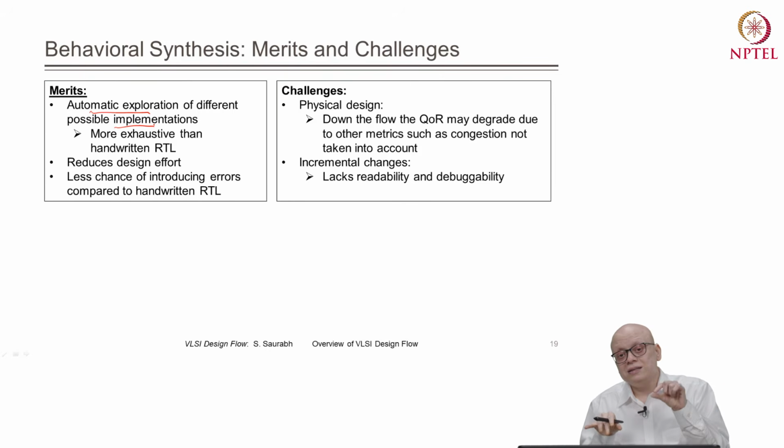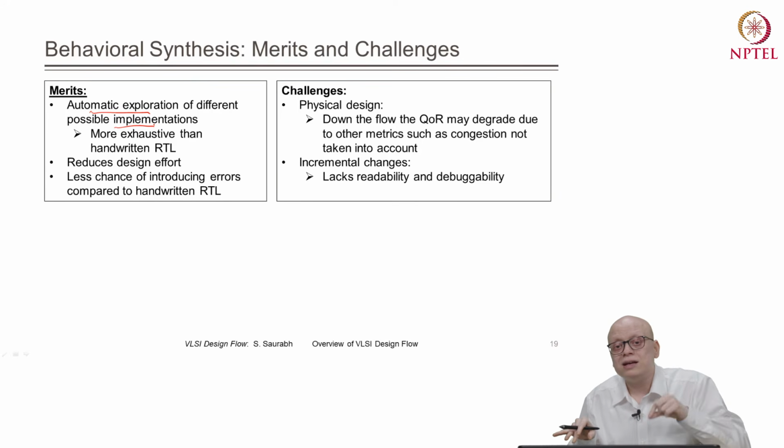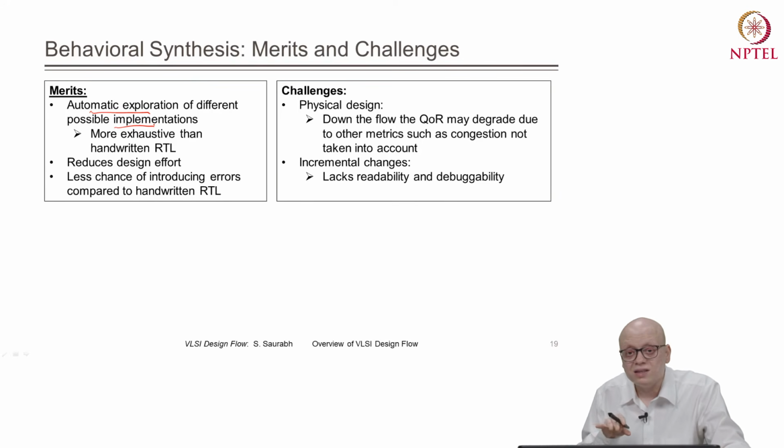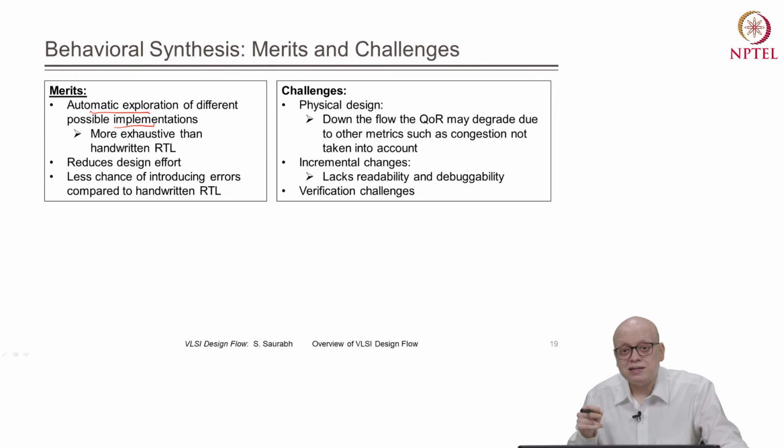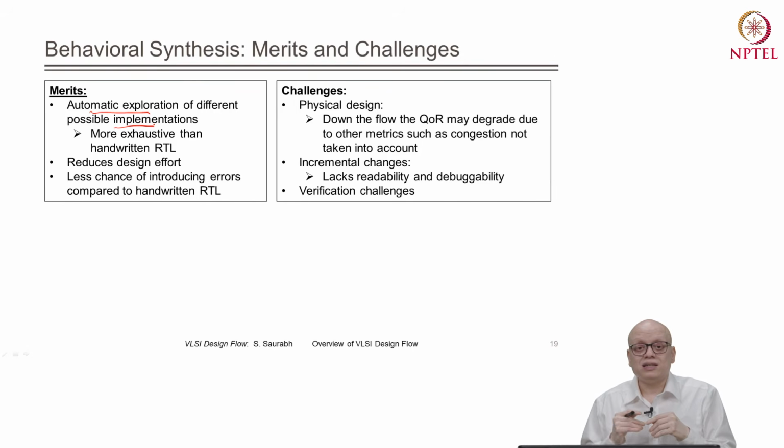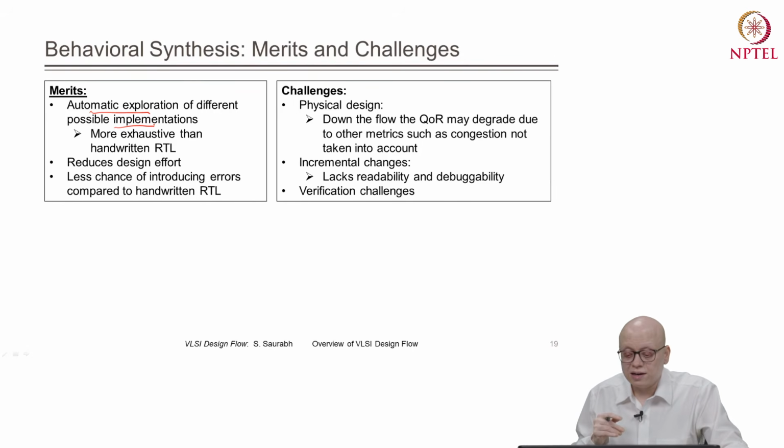A small change in the algorithm can lead to a very big change in the generated RTL, and therefore making small adjustments to the algorithm becomes really difficult with a behavior synthesis tool. And there are verification challenges: ensuring that the algorithmic description and the RTL actually match in terms of functionality. That is again a difficult challenge that needs to be tackled by the designer who is using the behavior synthesis tool.